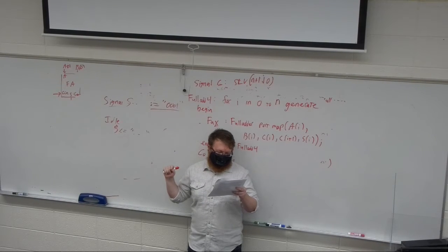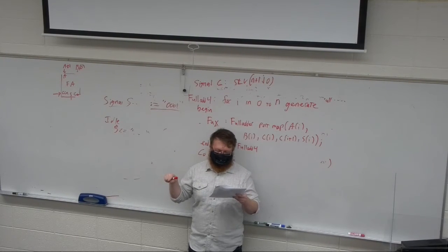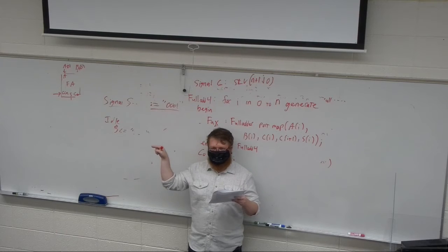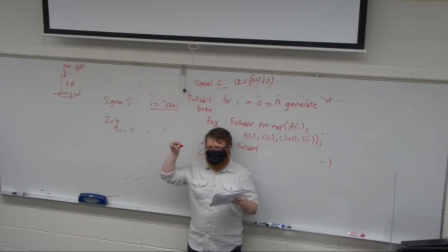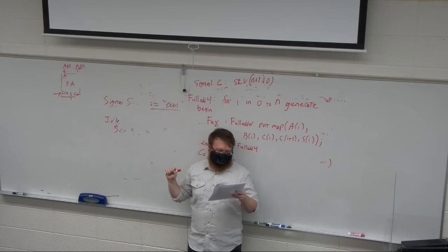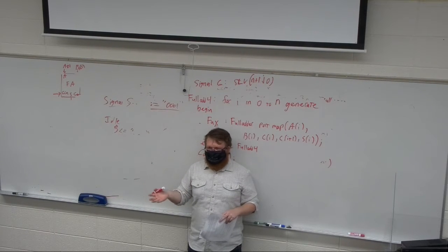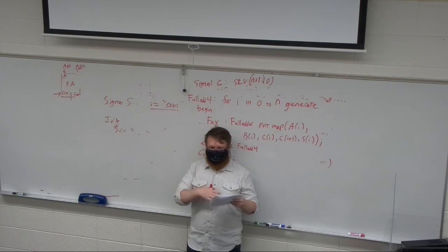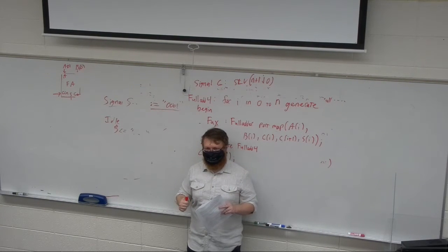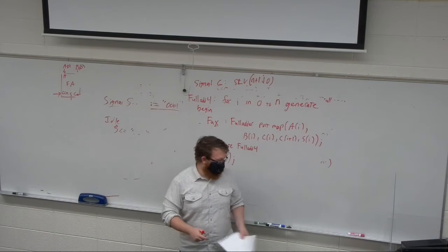The other one is the state type. I had TX instead of TX1. So you could either change all of the TX1s to TX or just change the state declarations to TX1. And then I used sdata0, which is an output, on the right side of an assignment, which you can't do. A couple ways to fix that. You could have changed it to an inout or a buffer, or you could have just declared it to the same signal that sdata1 was. There are a couple ways to fix that one. And that was the exam.